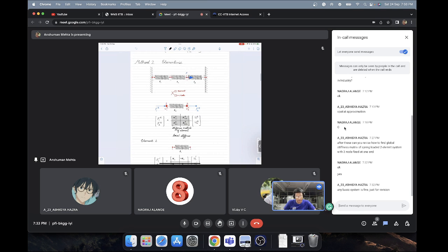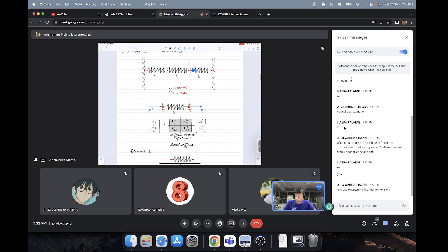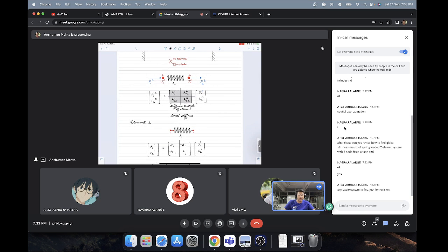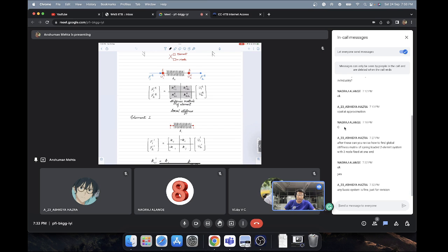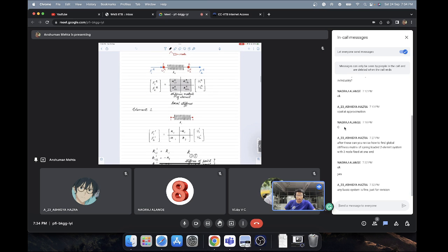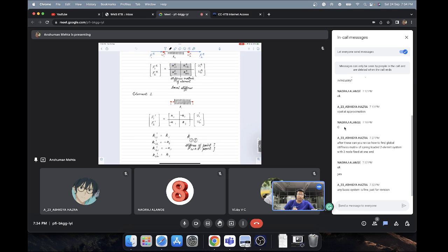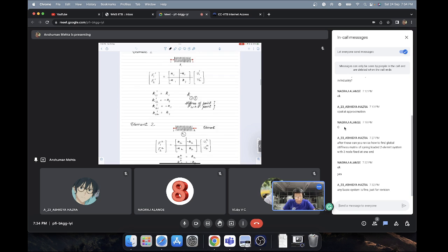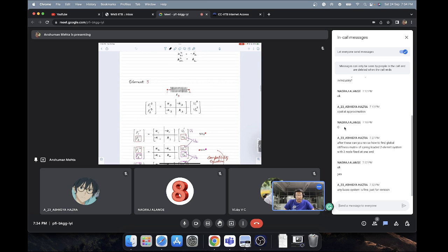The second method is element-wise. You take an element, and for one element you define everything. In this case, for one element, I have defined the forces, the displacements, and the stiffness like this. Having done this for one element, we move on to define the next, same element. If there is a repetition of behavior, we can put it in an organized way. In this example, all three springs have a similar kind of forcing.